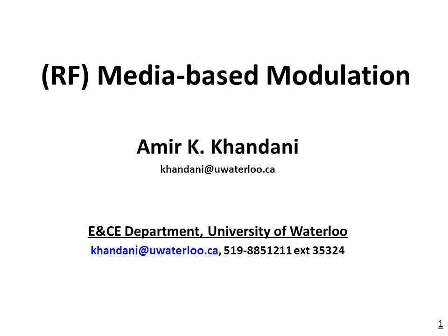I'm going to share some research results on something that I have called media-based modulation. It's a modulation technique which is based on changing the RF environment in the propagation channel from the transmitter to the receiver by perturbing the environment close to the transmitter antenna and thereby embedding information in the channel state, which can be detected at the receiver.